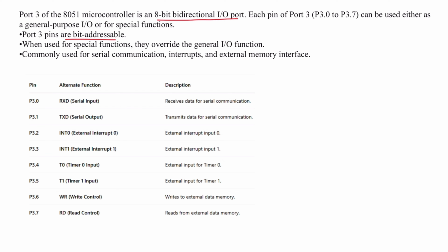3.2 is INT0, external interrupt 0. 3.3 external interrupt 1. 3.4 timer 0 input. 3.5 timer 1 input. 3.6 write control. 3.7 read control.